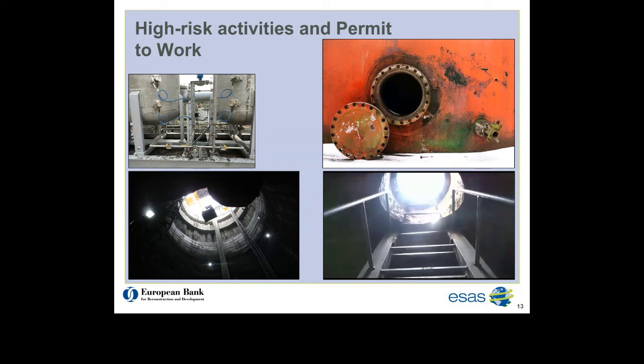Instead, workers are relying on verbal commands. Work being undertaken within the confined space outside of normal hours has no additional controls or supervision. At one point, a gantry crane is used to enter a large confined space, but there is no additional means of access and escape should the gantry crane malfunction.